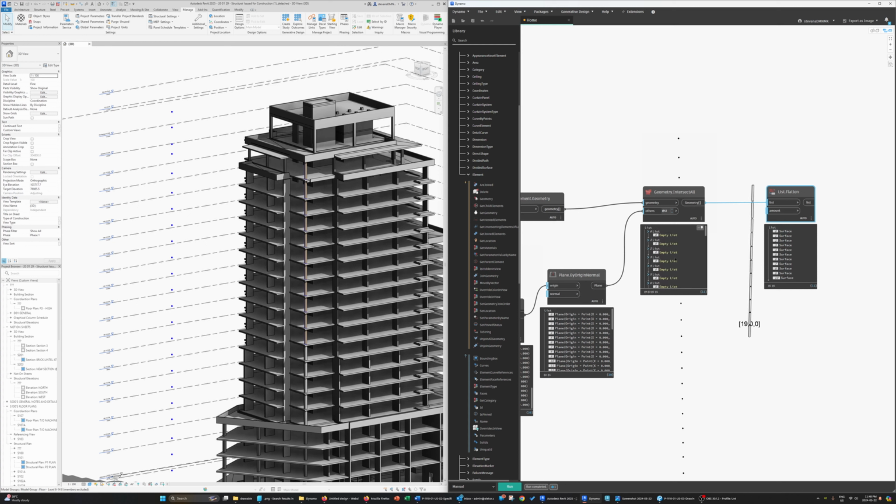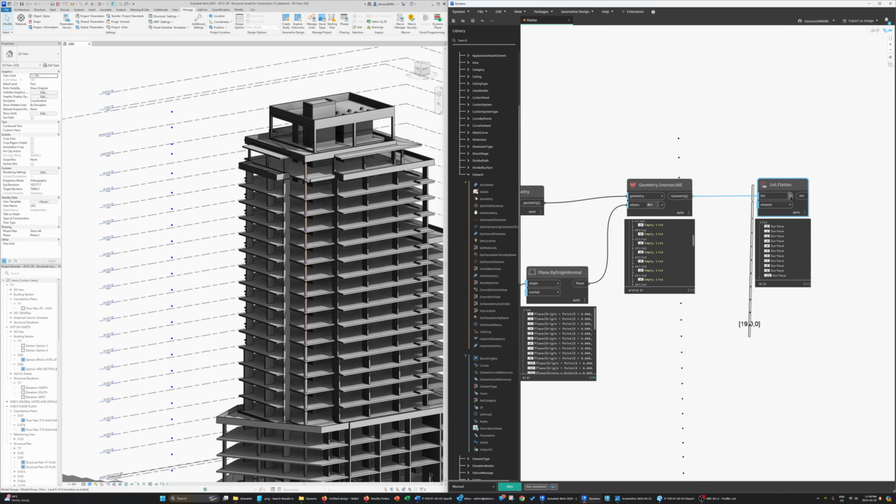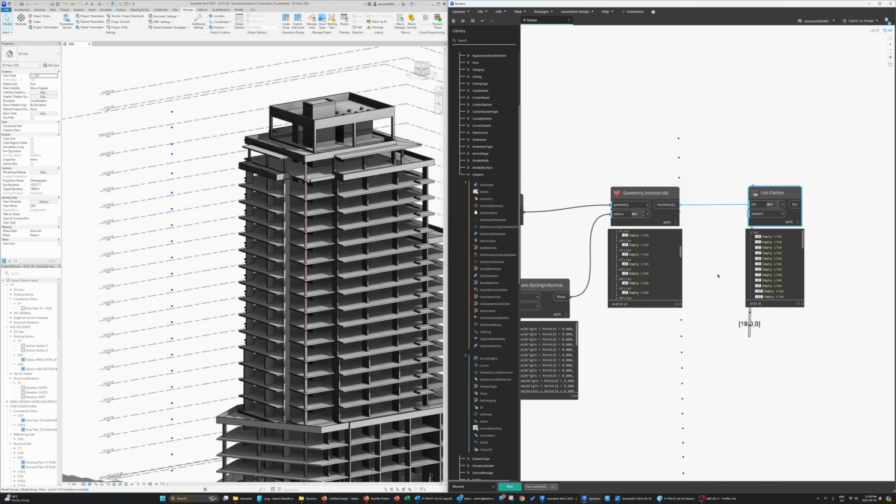I am going to have to flatten not my level 1 lists, but my level 2 lists. There is a reason for this, and obviously we have to understand how it behaves, but I have to look at this from a standpoint like this. Obviously, once again, I'm using this to extract the levels that it's interacting with. So right now, if I did my level 1, it would just extract the surfaces because the other ones are empty, so it's just not placing empty values. However, now, because we're going to level 2, it's telling me that it's an empty list, and then when there is something within it, it's going to show me that surface.